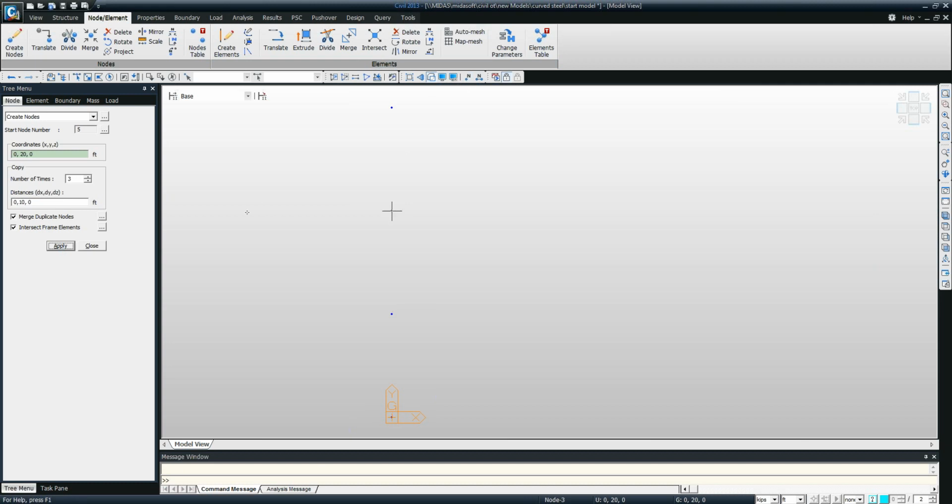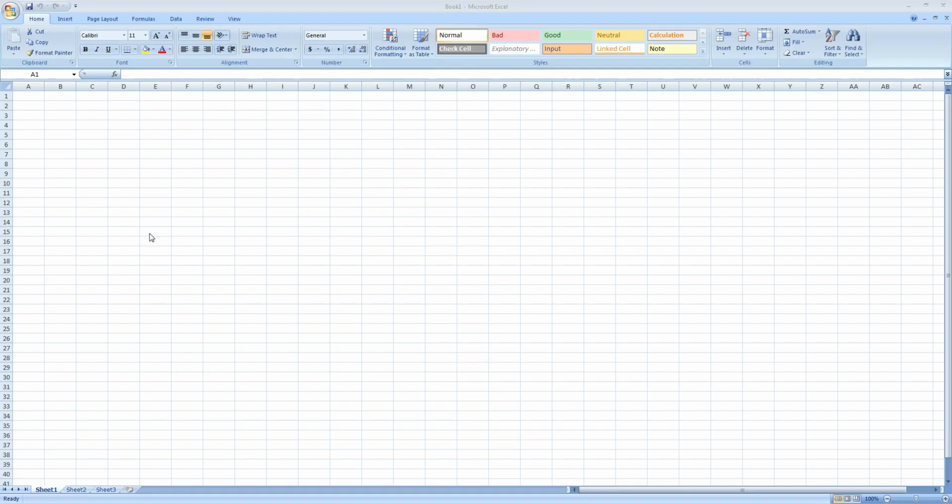Now I'm gonna extrude these nodes, and I'm gonna rotate them so that I can have more nodes. But what is the angle of rotation? So now let me compute the angle of rotation in front of you, so that you guys know how you can use the Excel computations for midas. So radius is 1250 feet, span 1 is 150 feet, span 2 is 180 feet.